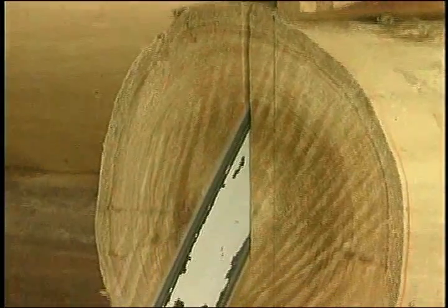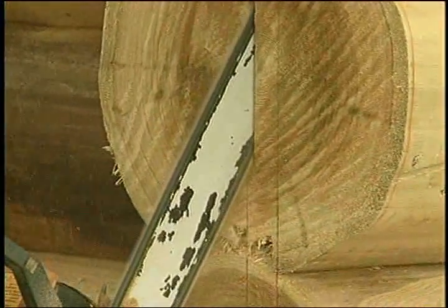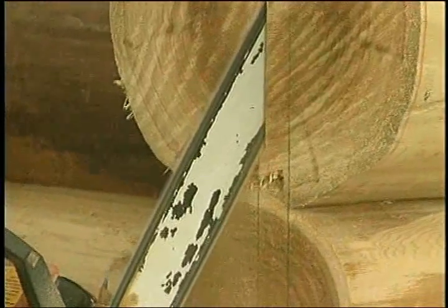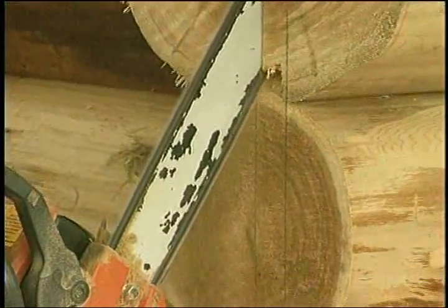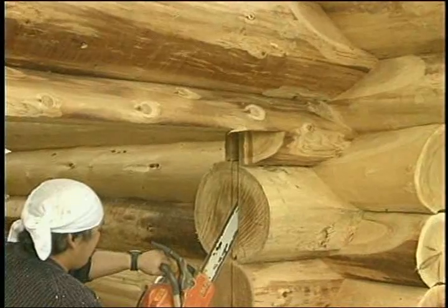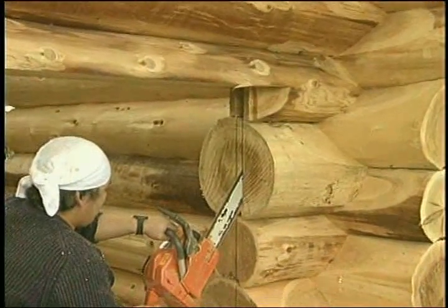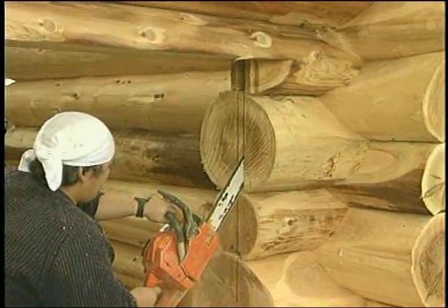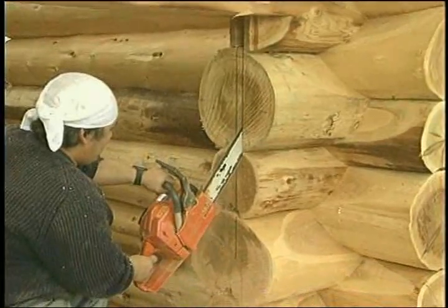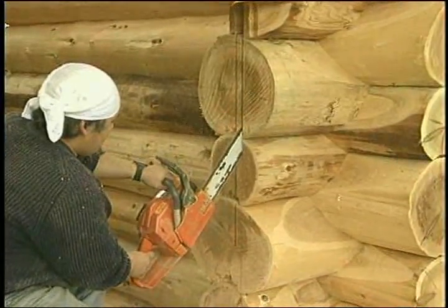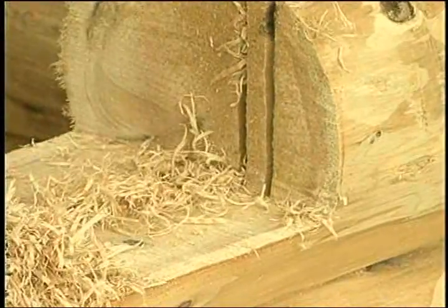Make the cut sufficiently deep for your material and parallel to the wall. There is a tendency to pinch the slot to the back. If you plan to place wires behind the key piece, make the slot deeper. The center of the slot can be cleaned out with several angled cuts, the same as we did with the header log.